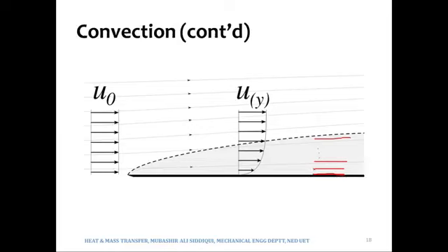And then the second layer. The velocity of the first layer of the fluid would in fact be zero if the plate, the surface, is stationary. The surface is this black surface. The first layer has the same velocity as that of the surface. If the plate is at rest, the first layer of the fluid will also be at rest, and the second layer of the fluid will have a velocity greater than zero.